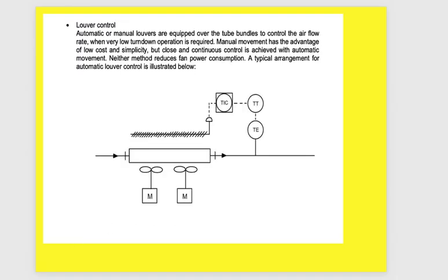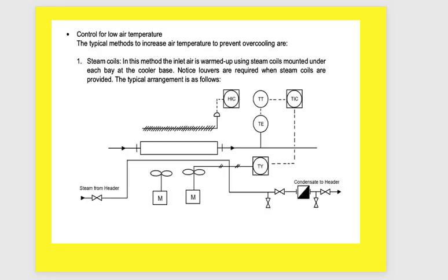And there is also louver control. We know that the air passes from top to bottom like this, and there is a louver. If this louver is vertical, it will pass all the amount of air. Okay, if it works with a narrow angle, it will decrease the amount of air a little bit and control the amount of air, controlling the temperature.